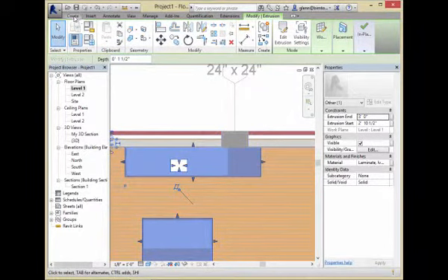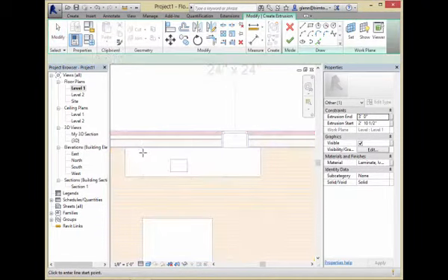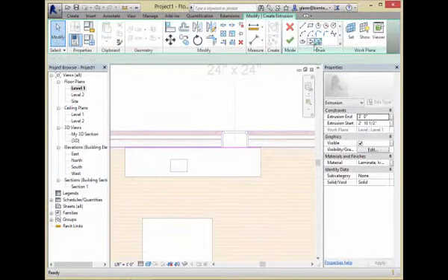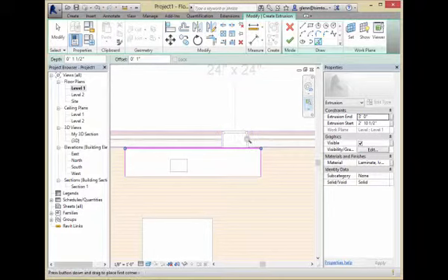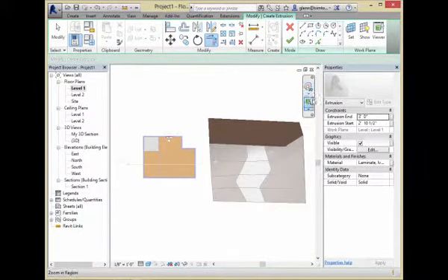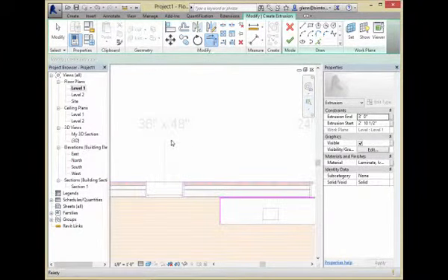So I'm going to go to Create, make another extrusion, and bring this on down. Actually, I should pick it. Picking would be a little bit stronger because then it would always stay aligned. Backsplashes are usually around 1 inch thick, something like that. Now, again, I need to use my trimming rules, TR for trimming. So I need that continuous loop. Come back over here. Zoom in even closer.